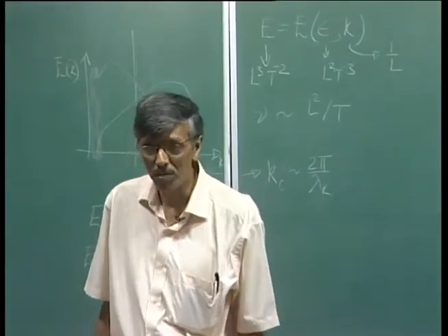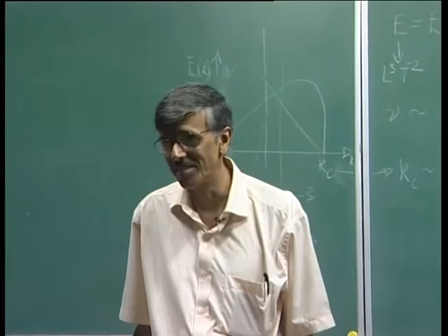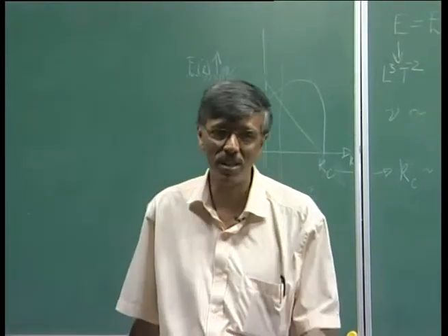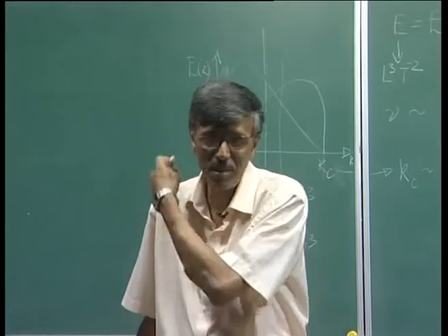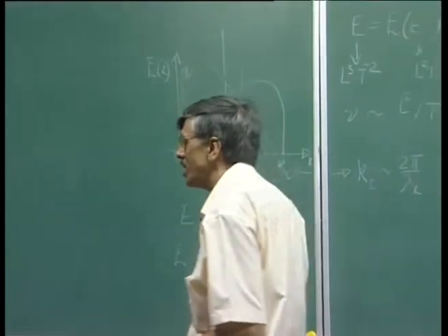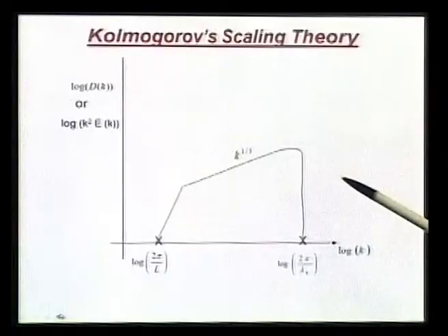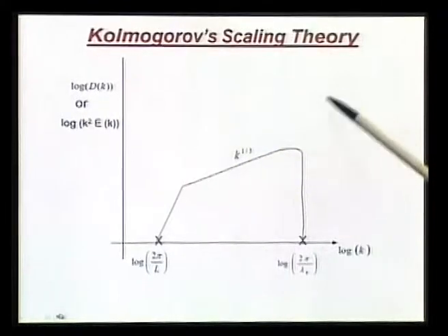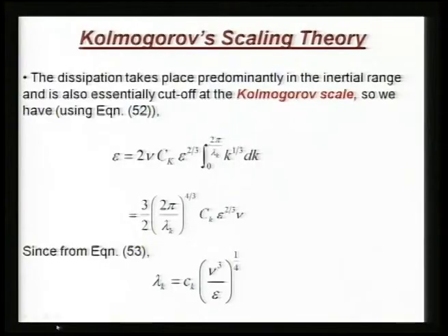So think of the subgrid scale modeling, it is not a trivial exercise. You will have to model it appropriately so that it mimics that D of k property. So this is something one must do when you generate a subgrid scale model for LES. Make sure that at least in the inertial range it should have this kind of attribute. If it does not, then you have a very poor model. Okay. So this is your dissipation spectrum.